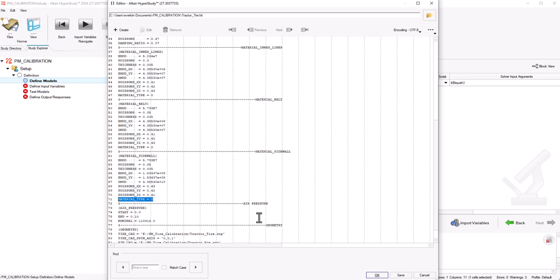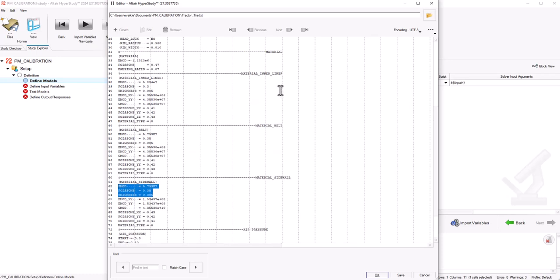So the way that the solver is set up for PM FlexTire, you can operate in a number of different modes. In this case, I'll be demonstrating the simplest, with a material type set to 0. That means that we're assuming that the material properties are isotropic. All the materials are the same in every direction. So that means that just the first three inputs taken from the sidewall, belt, and liner will be used. So E mod, Poisson, and thickness, E mod, Poisson, thickness, E mod, Poisson, thickness, and the material. Always all three of those are used.